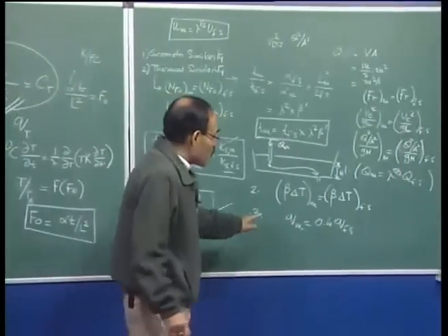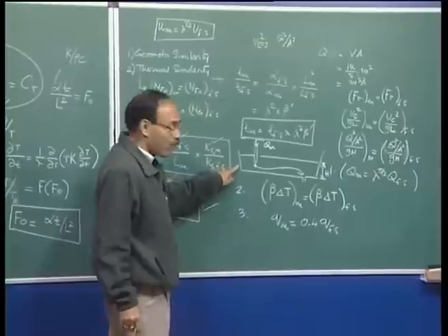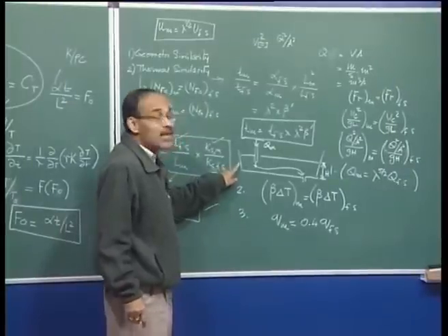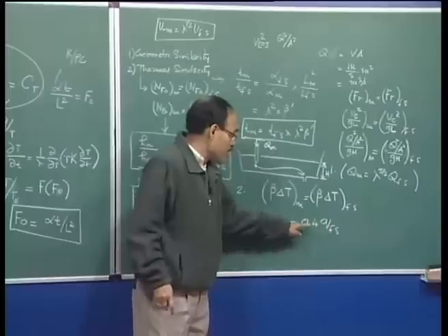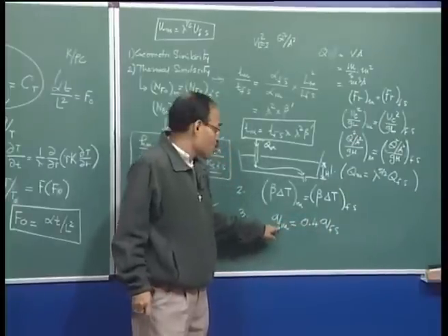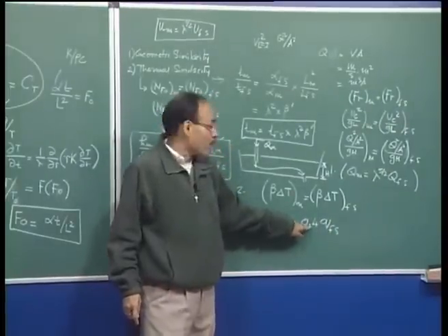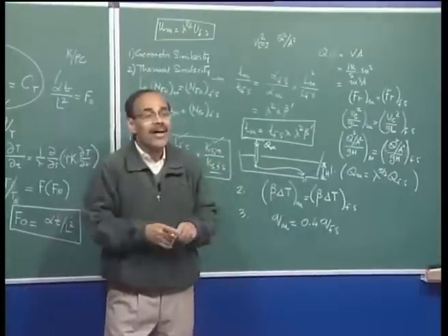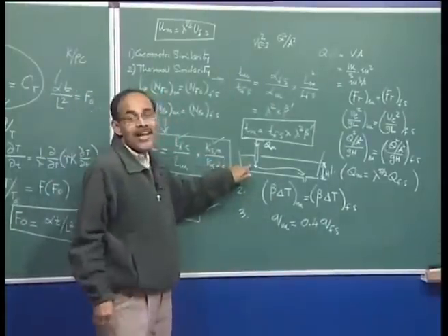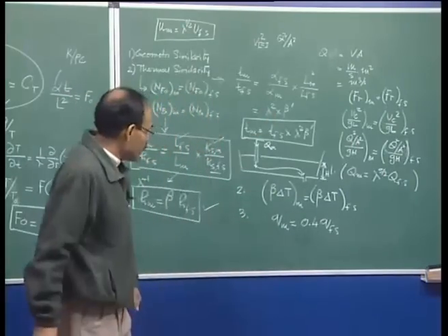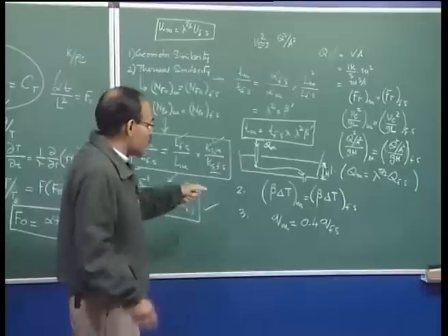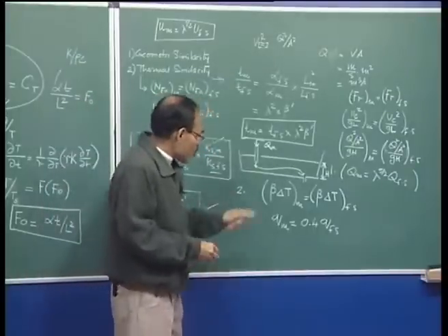Now, as I mentioned, in industrial surfaces we can typically have 5 to 10 kilowatt per meter square as the heat flux. If it is 10 kilowatt per meter square, then what we require in the model is 4 kilowatt per meter square. If I have a glass vessel and water at 100 degree centigrade, I cannot get 4 kilowatt going out of the liquid water bath through the glass vessel itself. So, this condition can be satisfied.